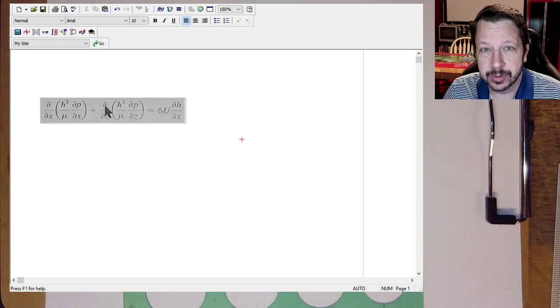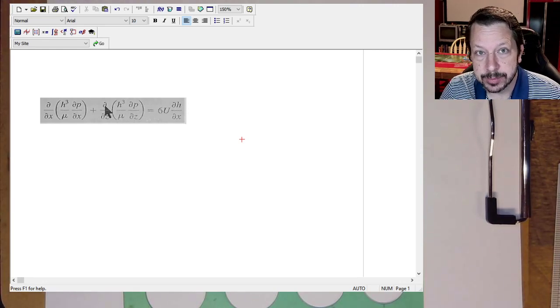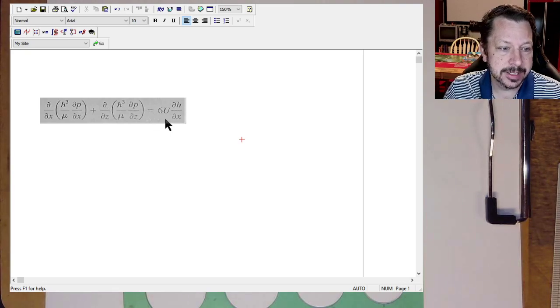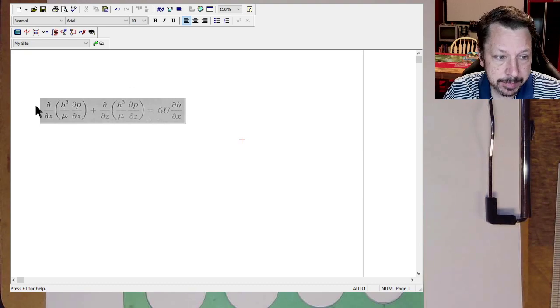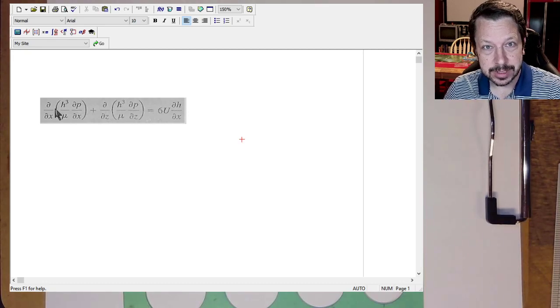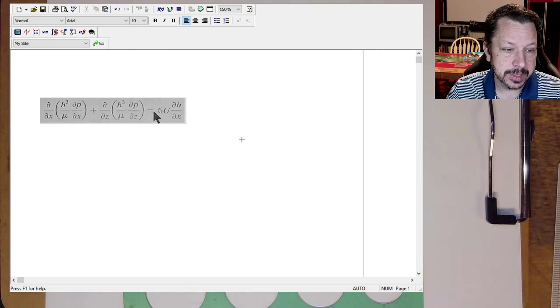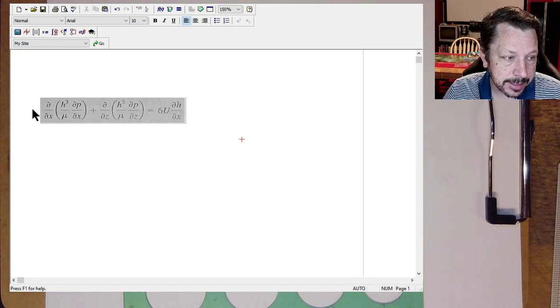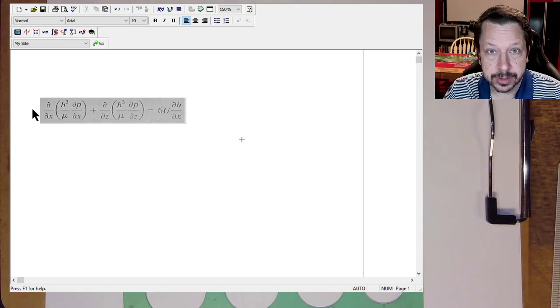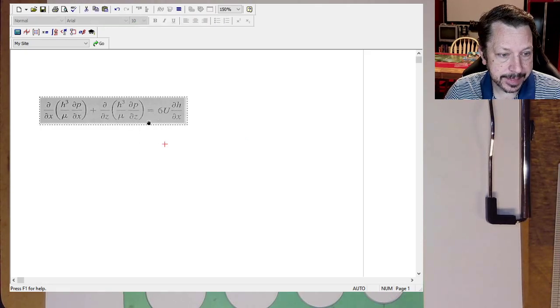So side flow means the oil leaks out the sides. You know, there's no caps on the end of the bushing or anything, so some oil lubricant leaks out those sides. So this equation accounts for that. The problem with that is there's no analytical solution for this equation. So you have to do some tricky math and a lot of different things to figure out some analogies. They even mention electrical circuit analogies on how to produce a solution to this, or at least an approximation to it. And so that's been done and encapsulated in charts, lots of charts. We looked at one of those charts last time. So that's what we're going to do this time.